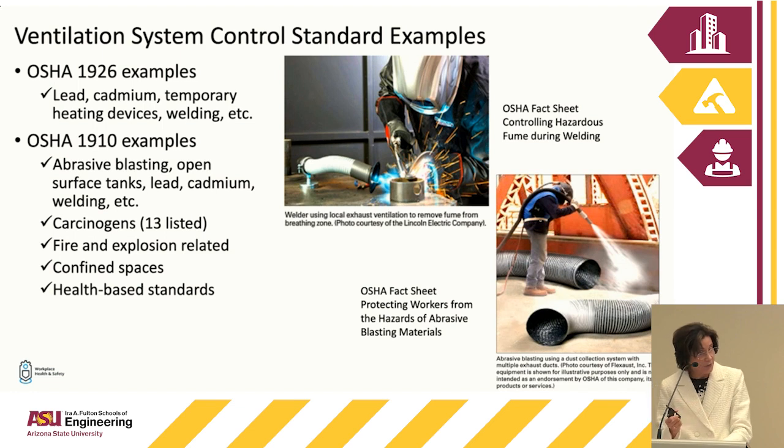So are there requirements in OSHA standards that you have to use ventilation systems? There are several standards. There is ventilation system information in these OSHA standards. There are the 1926 examples, and then some examples in 1910. However, nowhere in those standards does it require that there be a risk assessment during design. It's done after there's an exposure event. Then we should be using ventilation systems.